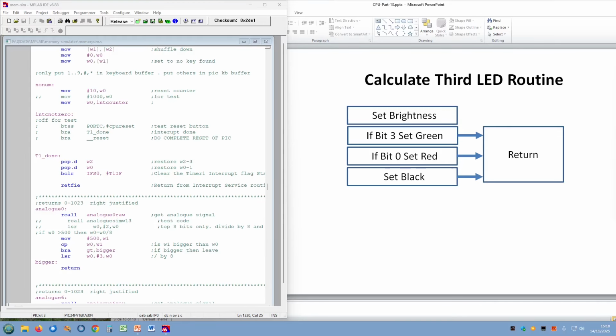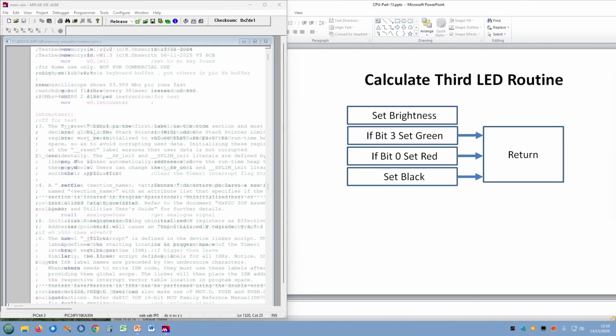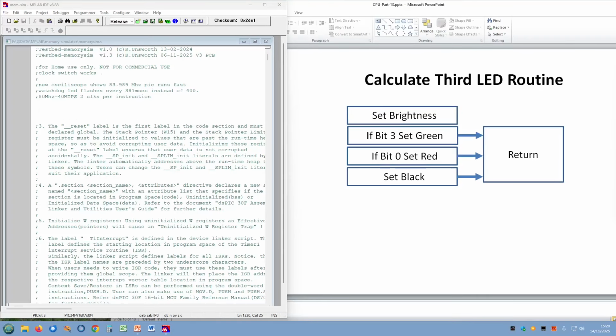The actual speed control is biased to one end so that most of the sweep is from going slowly to faster. You can see the LEDs going, but once the LEDs are going too fast for you to see what's going on, there's no point having any speed control there. So this is all biased up one end through the signal that's fed back for the speed control. So it's shifted over and 500 added, etc. So that covers all the bias and glue logic in the microcontroller on the motherboard.